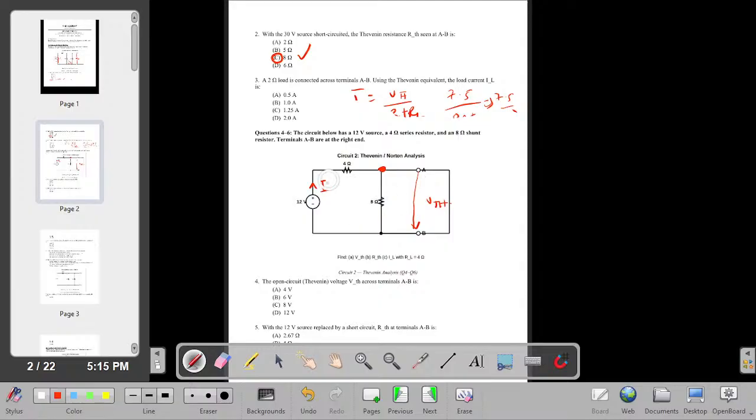Because of that, our effective circuit lies here. In the presence of our source, 4 ohm and 8 ohm are in series. Please take note, there is a tricky thing here. These two are in series in the presence of our source. In the absence of our source, they don't become in series. The reason they are in series in the presence of our source is that the electrons will flow here, and upon reaching here, they have no option because this is an open circuit, right?